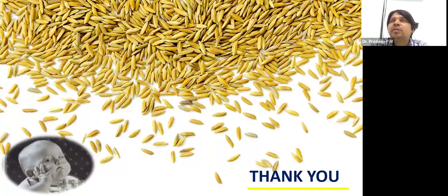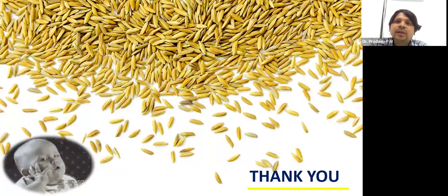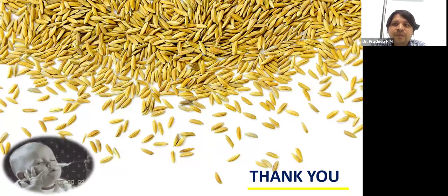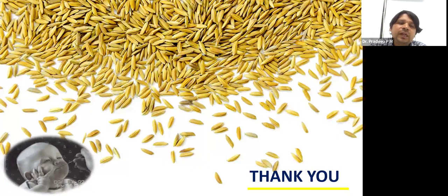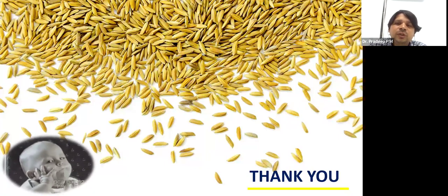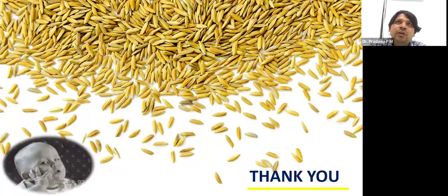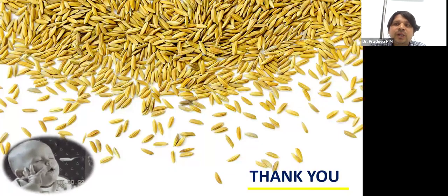So what we need to do is we have to restrict the moisture buildup and the temperature gain within the small pockets of paddy. So to overcome that, regularly we mix the paddy from top to bottom so that this accumulation of heat or the moisture buildup is reduced.